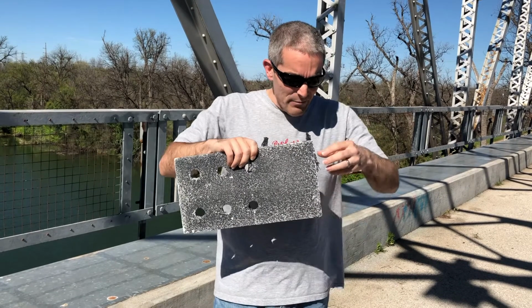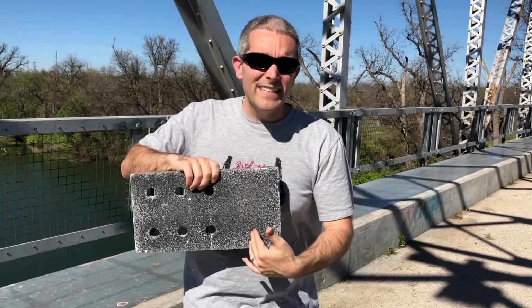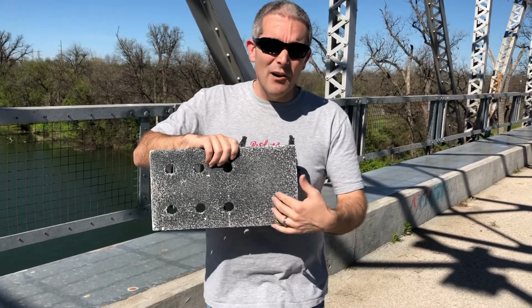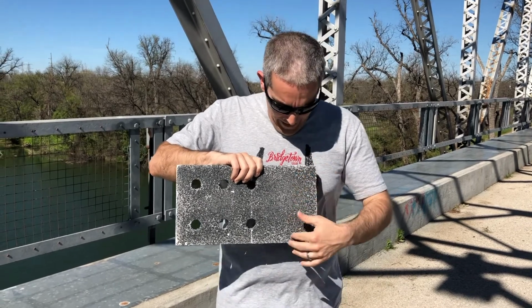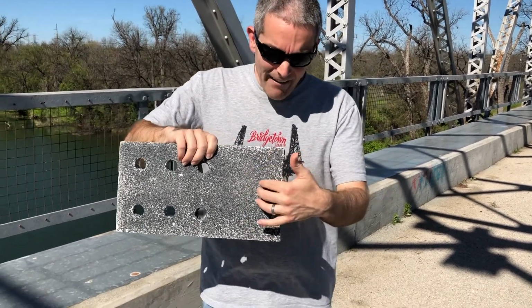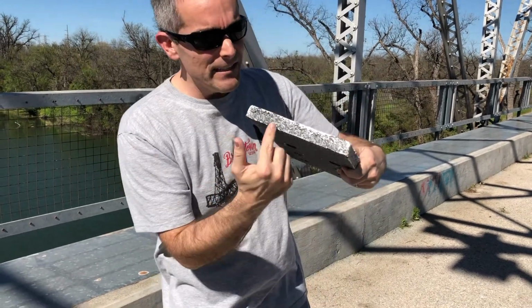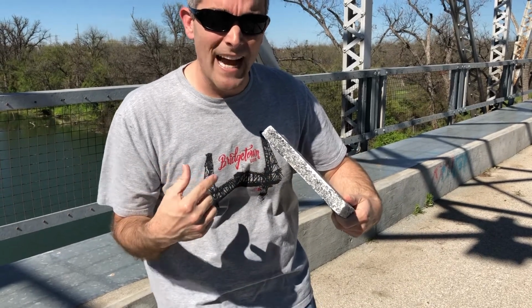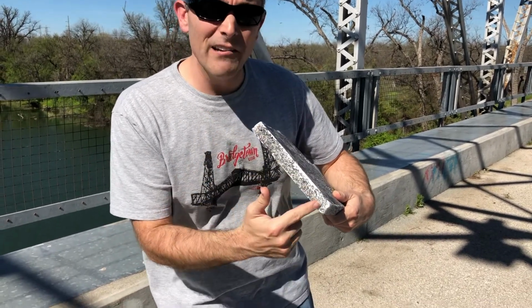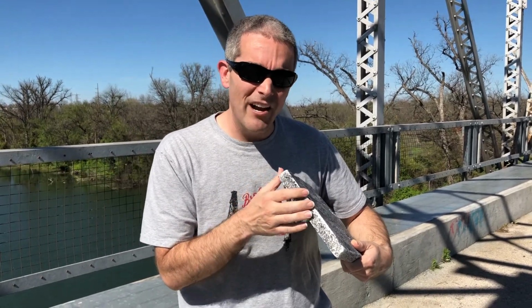Now, as we pull, we might expect that somewhere over here, this gusset plate will yield. And so when that yields, it will cause stretch, right? Now, that area that's stretching, that area is this surface here. And so looking at that, that's this cross-sectional area that is subject to yielding. So when we go to come up with our design strength, we're going to use what we call the gross area of this cross-section to come up with how much strength this can hold for the limit state of yielding.